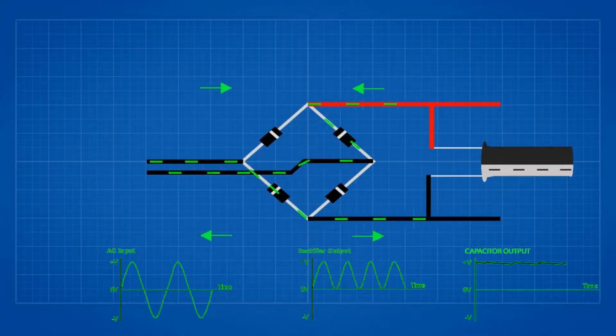But most of the things powered by electricity run on direct current. So we need to convert alternating current to direct current, and we are going to do that by using a bridge rectifier, which consists mainly of 4 diodes, and we will use a capacitor as well. Diodes have the ability to allow current to flow through them in only one direction. So we will get a great DC supply from the bridge rectifier.